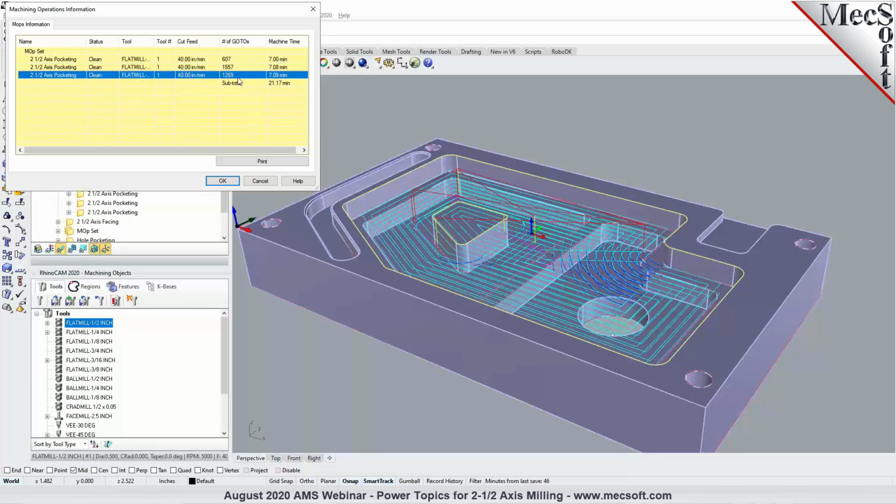And the last one you're seeing here is the arcs being fit to the toolpath. With the tighter tolerance and arc fitting, the number of motions is about 2 times. Fitting arcs to toolpaths also makes it smoother and easier on the machine to work with. So the tighter the tolerance, the more go-to motions and more lines of code in your posted G-code or output file.